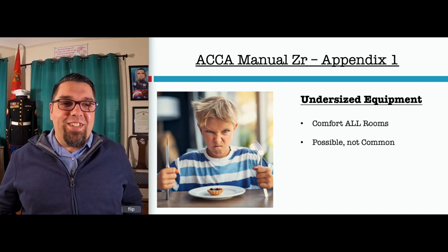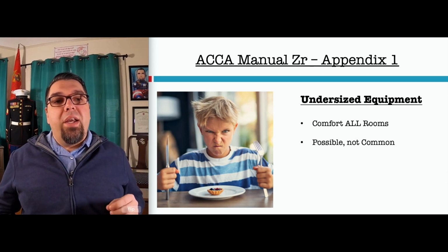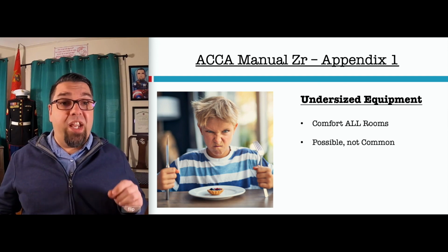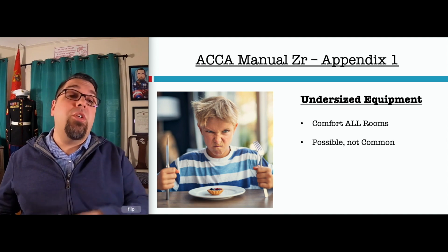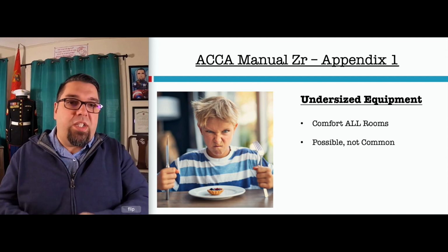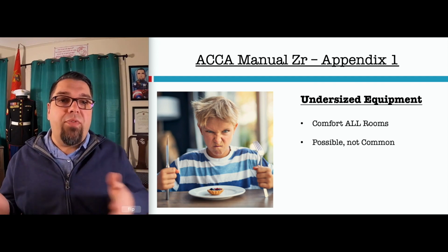Everybody's scared of this: undersized equipment. Right? You do a load calc, you put it in, and now it's too small. And guess what? It's your fault. The homeowner's going to hold you responsible for this. But even though this is possible, it's very uncommon. And if it is happening, it's because you're not doing your load calculation correctly, right? It's obvious, because of the ability of oversizing. Think about how bad that has to be for you to be too small in that process, right?